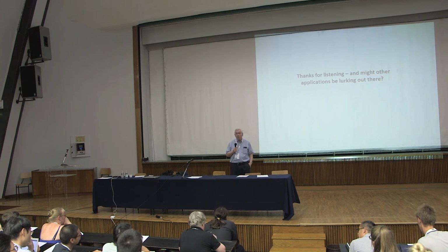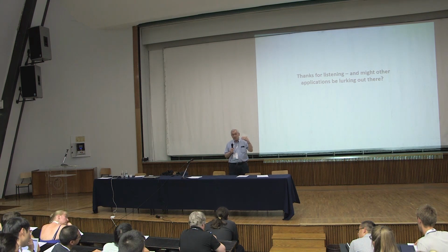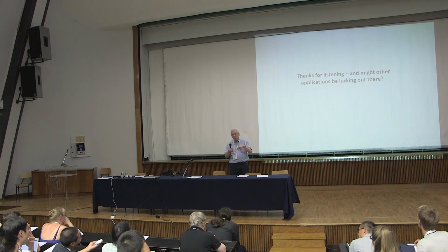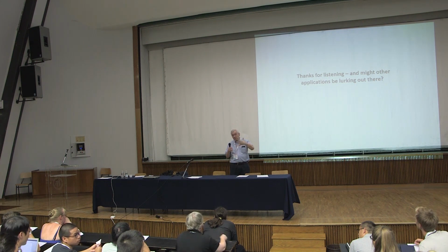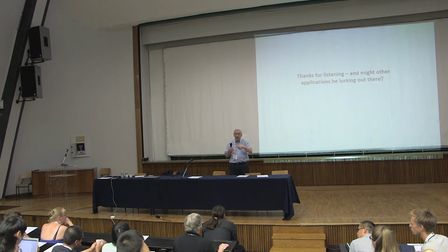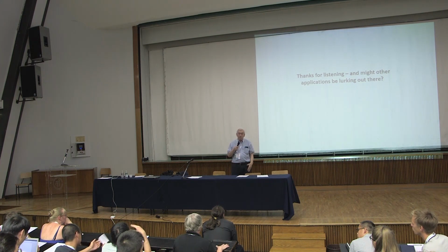Yeah, maybe. To the extent that you're willing to treat the places where the dislocations have glided as something that slips either freely or under constant shear stress, and then there's something blocking the array of dislocations at the tip, then you could take the point of view that you've got either a freely slipping crack or a crack that slips under essentially uniform shear stress. In both cases, the J-integral would apply. I don't know if anyone has applied it to that, but do it.